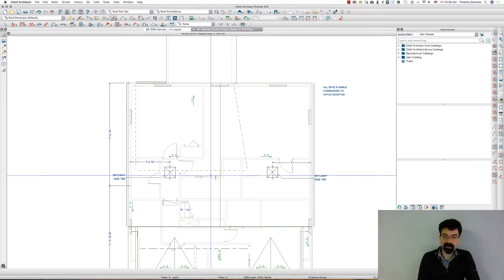Unfortunately, it is a CAD line. It's not connected in a BIM sort of way or a modeling sort of way. So if you change the shape of this roof, yes, you will have to change the shape of the CAD line. But that's where the roof is, so I don't plan on changing the shape of this roof. Now, I guess a caveat is that I did change the shape of the roof where I wanted it to be before I drew the line.